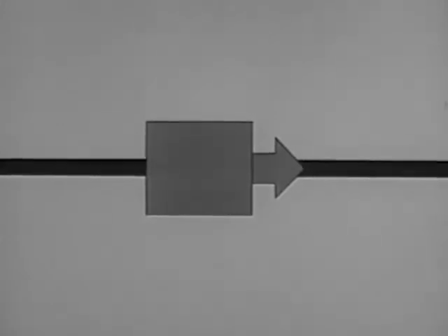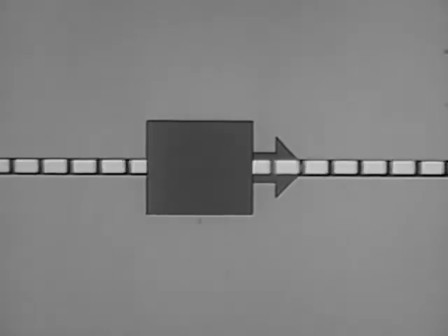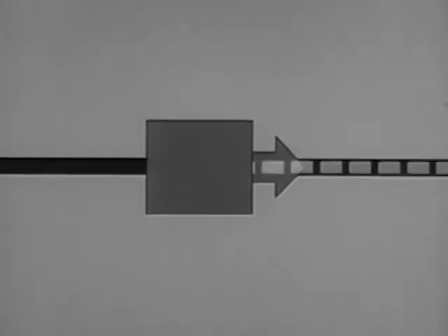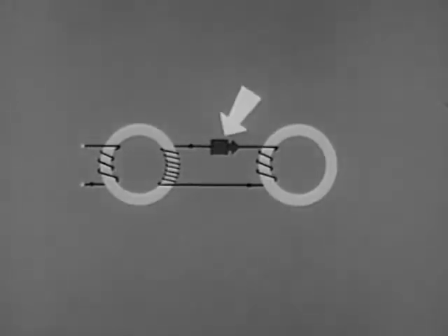Any unidirectional device or arrangement will serve the purpose, and we'll symbolize this with a general symbol for one-direction flow. The arrow points in the direction in which it allows the current to flow. Current coming the other way meets the back resistance of this device and is blocked. With such a device in position in the circuit, the second core is effectively isolated from the first.